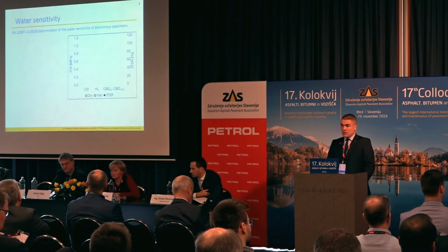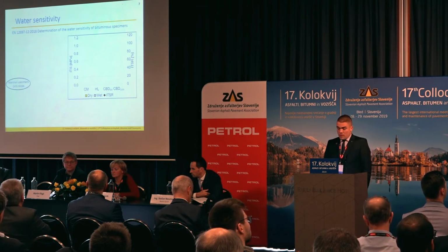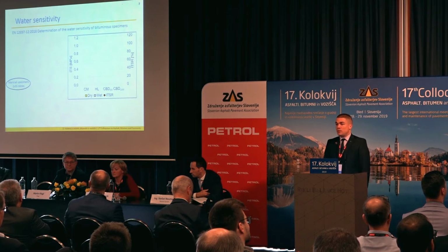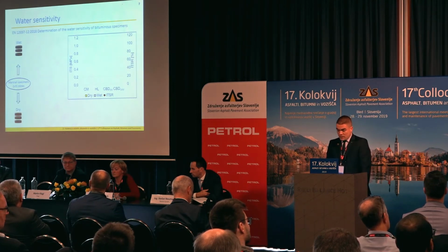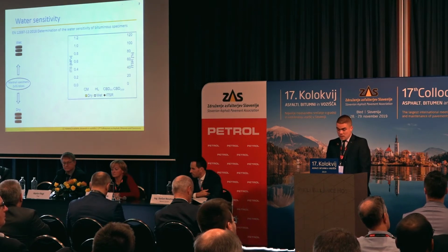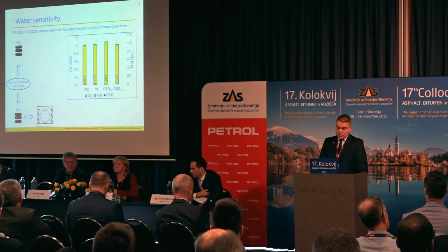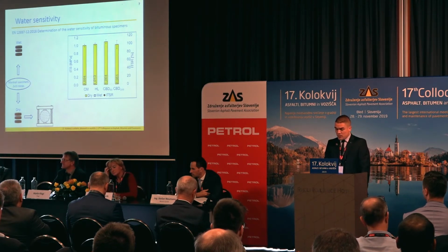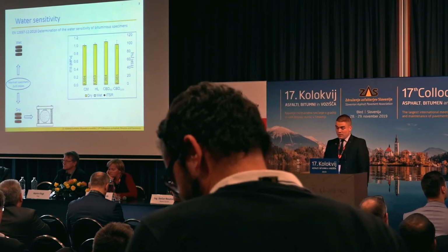So the first test was water sensitivity according to the European norm, where Marshall specimens were compacted with 35 blows per each side. Samples were divided into 2 subsets, and the indirect tensile strength of the dry or unconditioned subset was determined, showing that all of the mixtures have more or less similar ITS values.